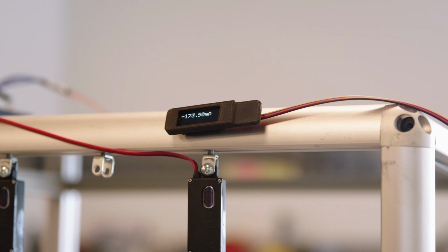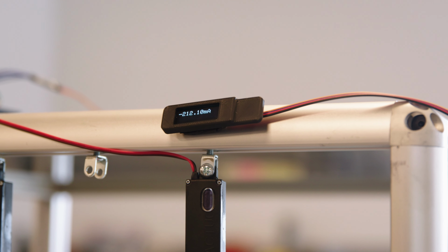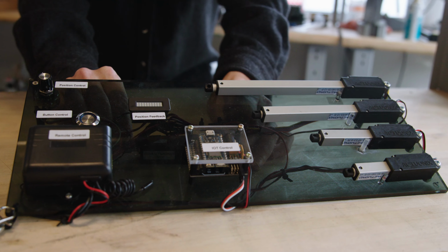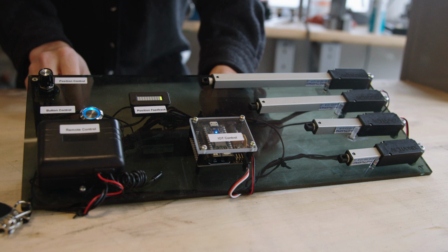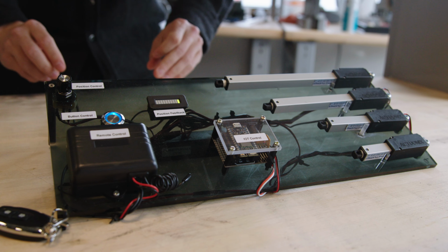For a more accurate count, you can use a counter and magnet switch. Mount the magnet and switch so that the counter increments once per cycle. When the actuator fails, the count will also stop, and you'll have that recording which you can check and record.